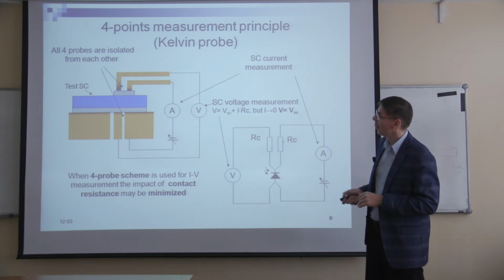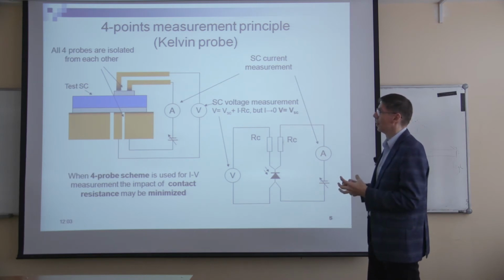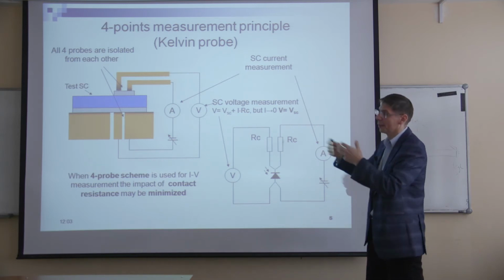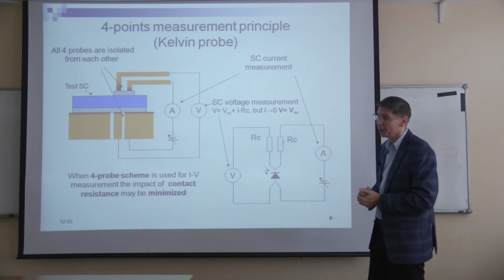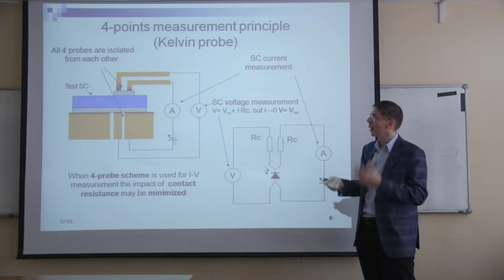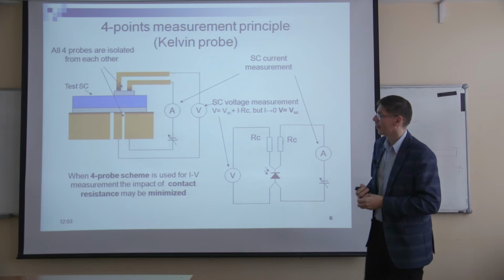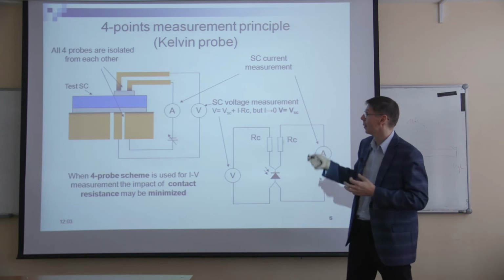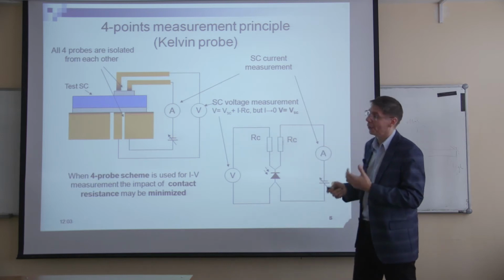Normally you set the voltage value, and then the source meter tries to find the condition which corresponds to this voltage, and actually it tries to pass some current. So in principle it's okay, it's quite easy, so you don't care about the real voltage or the real current of this source, and you just fix the pairs of the value of the current and value of the voltage.